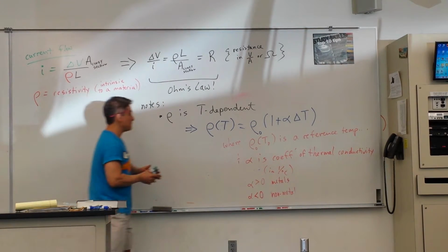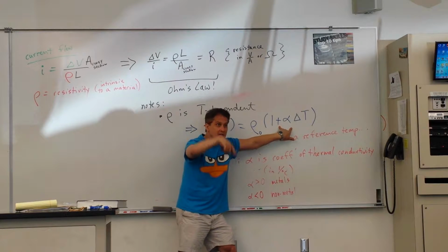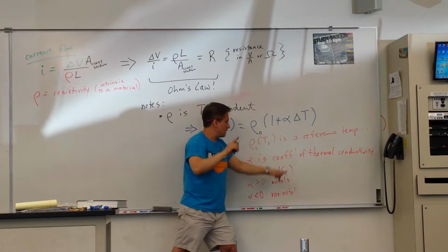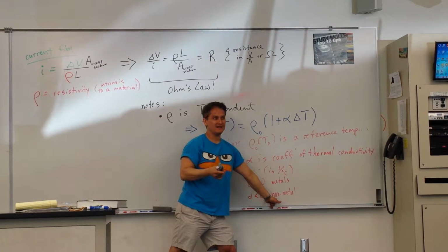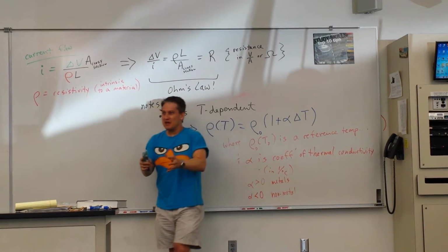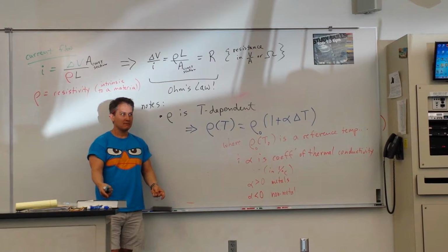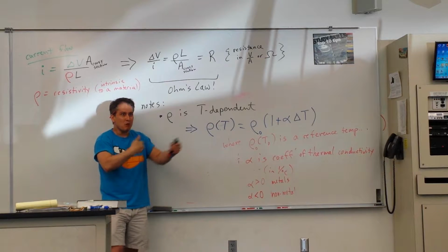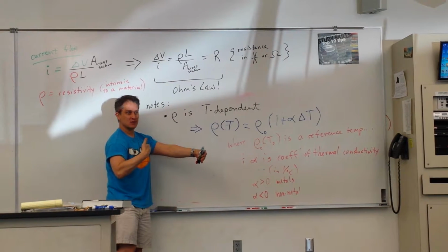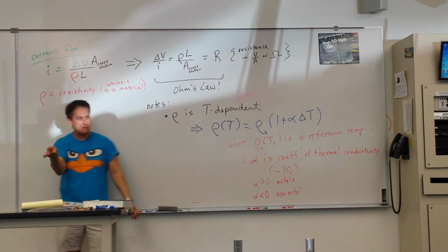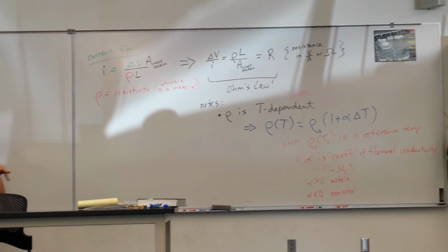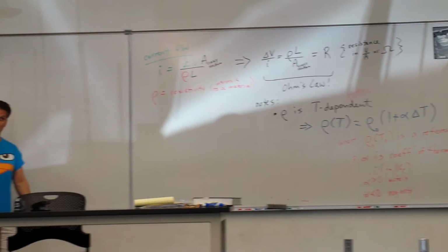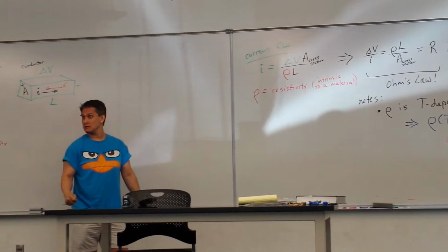And that's important because what it means is that when metals get hot, the resistivity and the resistance goes up. When nonmetals and insulators get hot, this one kind of makes sense. You're shaking it so much, it's a lot easier to get the electrons off. But when you have a conductor and the electrons already come off easy, the more you thermally agitate, the more barriers you put in front, the harder it is to push those electrons through. So for opposite reasons, increasing temperature allows charge to flow more readily through non-conducting materials, and vice versa for metals.